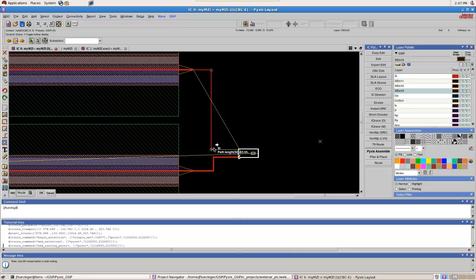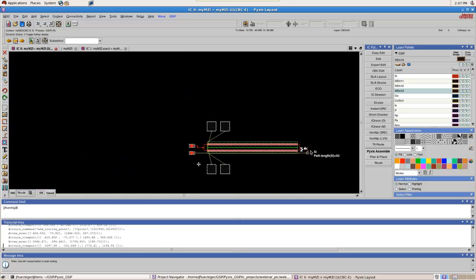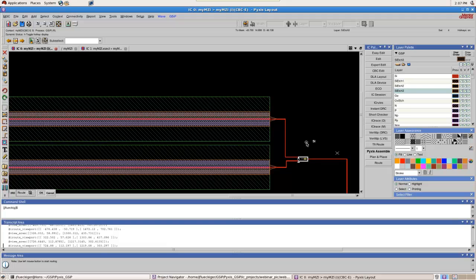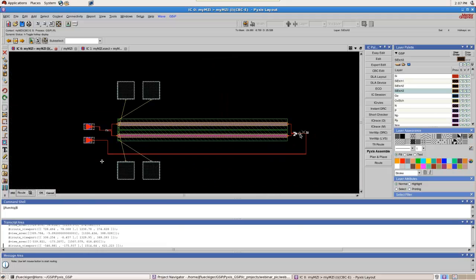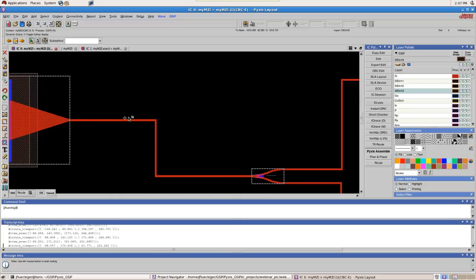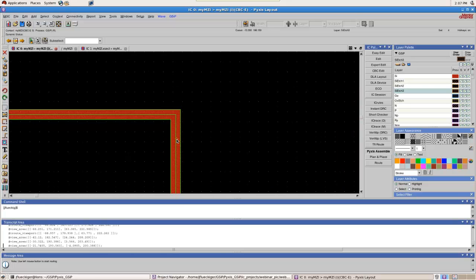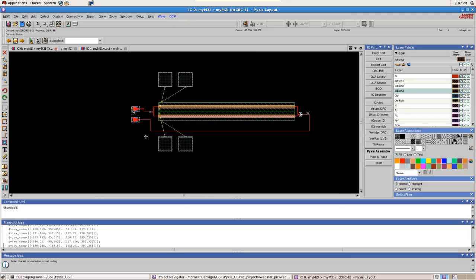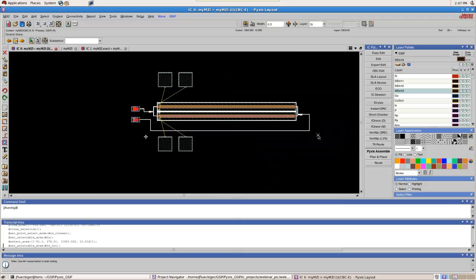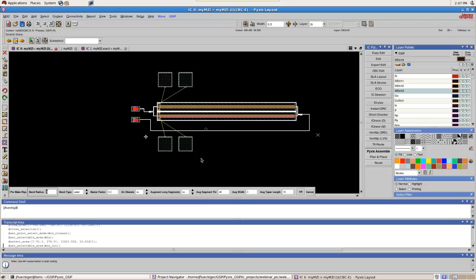So connecting to our combiner here, and now we're gonna go all the way back to the output grating coupler. Now we have the waveguides, but obviously we need to convert these sharp corners to bends, so that's a problem. So we have a huge amount of losses here, even assuming this will even work. So what you can do now, you can select all the waveguides, and then using some of the tools we have for the Photonics package here, we can call the make PWG function.